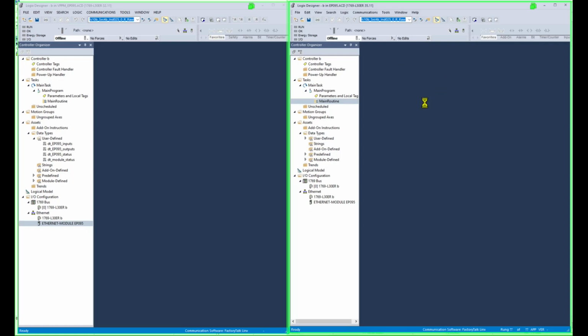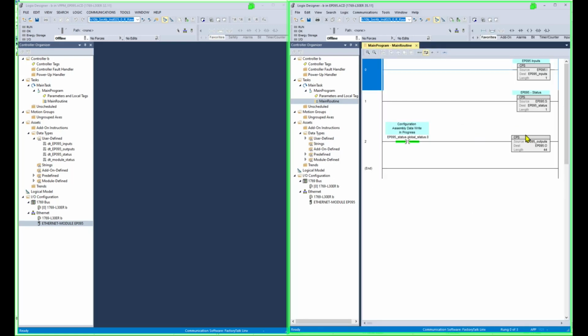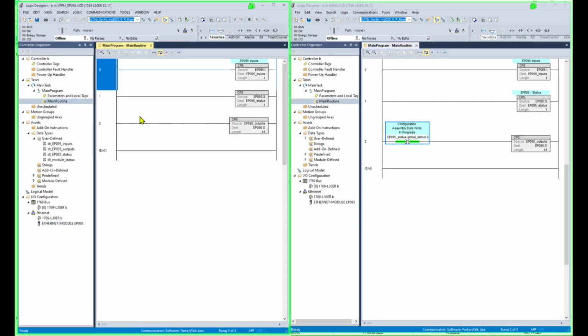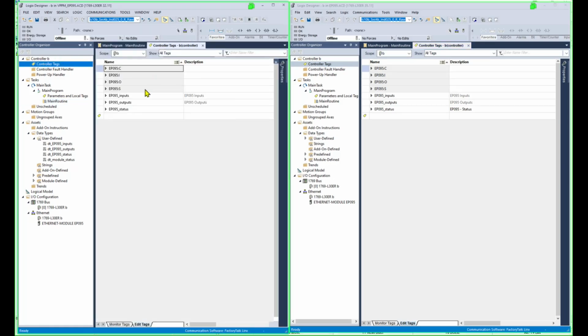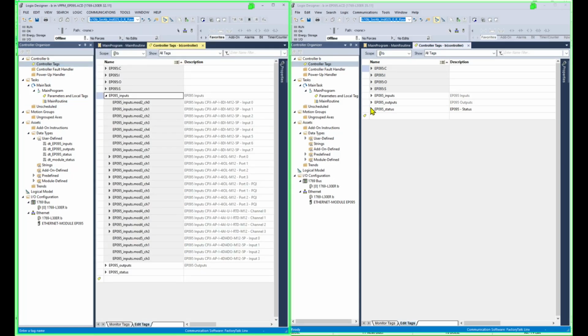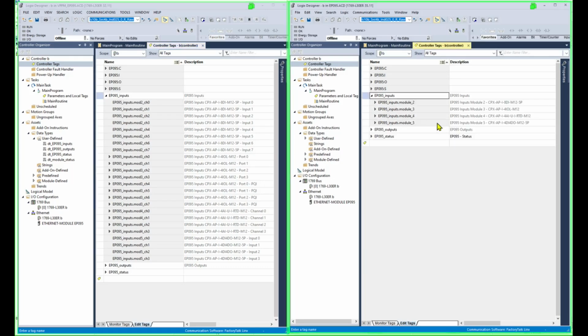The right hand side is the PLC export from the web server. It has this extra bit. On the left, we don't have the bit, but the mapping itself looks identical. The problem is that the tags are different structures. See how the data type structures are very different?